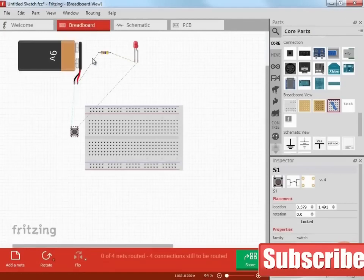The little dashed lines show our circuit connections by what we would call air wires. They just show the circuit connection but aren't the actual connections yet. We're going to have to make those. So let's start moving our components around and actually wiring up our circuit. We'll move the switch.